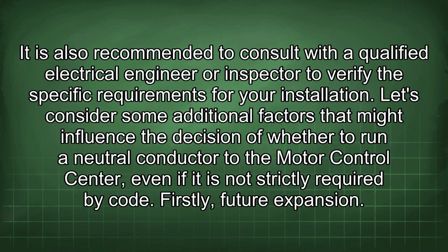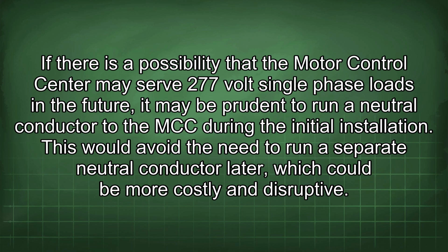It is also recommended to consult with a qualified electrical engineer or inspector to verify the specific requirements for your installation. Let's consider some additional factors that might influence the decision of whether to run a neutral conductor to the motor control center, even if it is not strictly required by code. Firstly, future expansion. If there is a possibility that the motor control center may serve 277-volt single-phase loads in the future, it may be prudent to run a neutral conductor to the MCC during the initial installation. This would avoid the need to run a separate neutral conductor later, which could be more costly and disruptive.